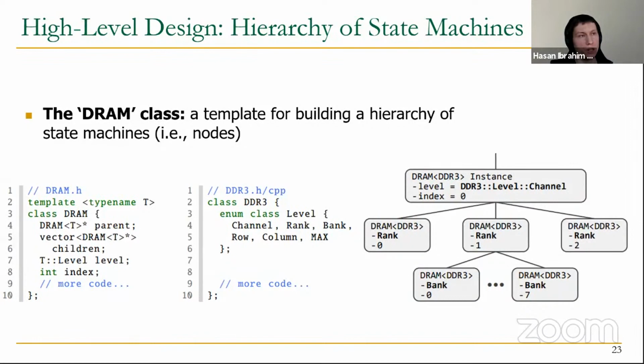Sometimes those chips operate as two different ranks. Different from channels, in two different ranks, chips are still independent from each other, but they share the same pins, so they share the same interface to connect to the CPU. And banks are basically different groups of cells that are implemented inside every DRAM chip.